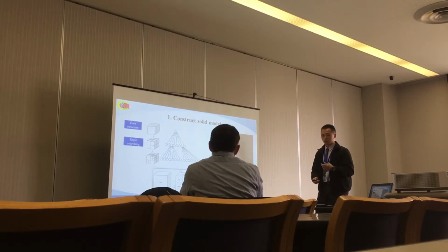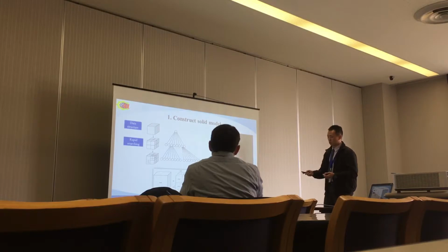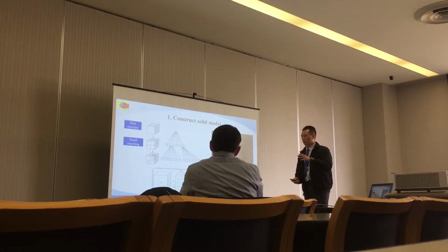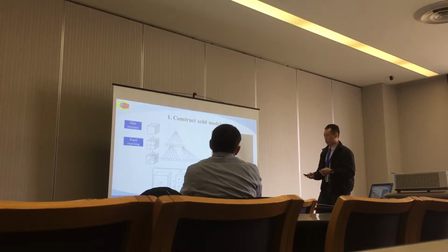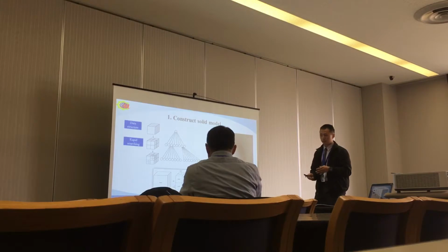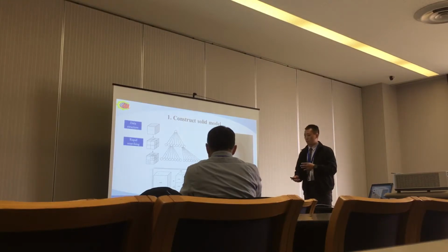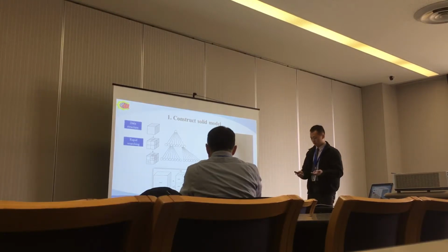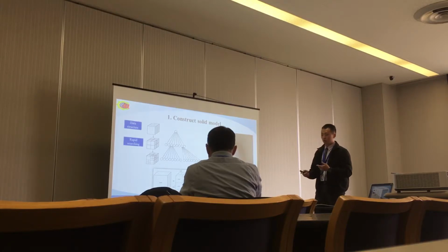Now we wanted to know how the octree can help us while we construct our solid model. So here is a tool model. It's a top view. And here is a workpiece model. So when the tool model collides with the workpiece model, the algorithm will start to search those intersected voxels in the octree, then subdivide them into smaller voxels. By doing so, we can save more time on data searching, because every voxel contains vertices and triangle isosurface information, which will be mentioned later on.